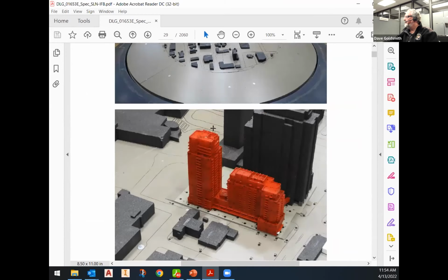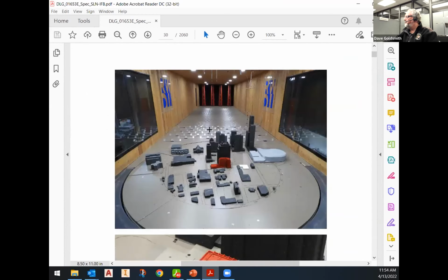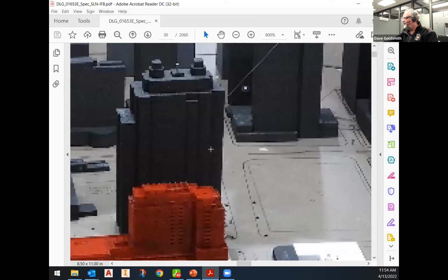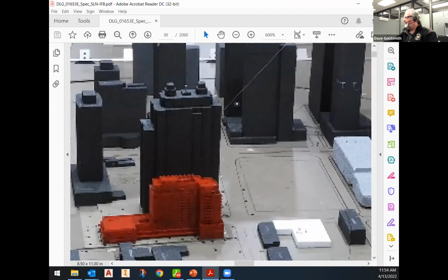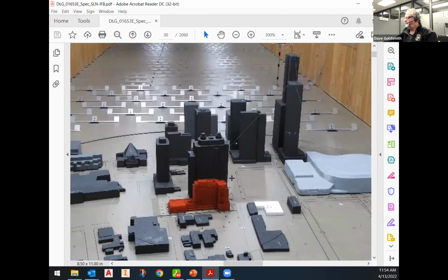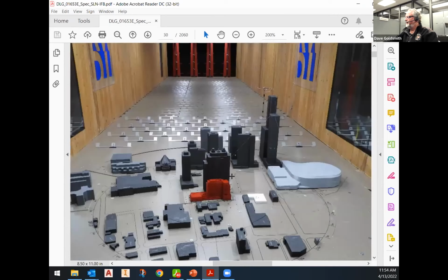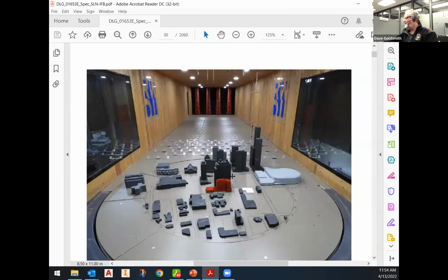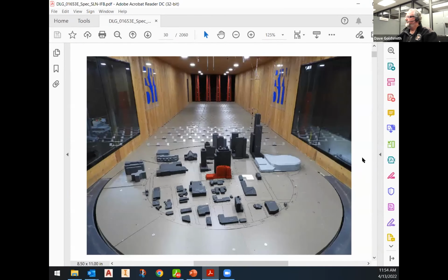So they want to be conservative in all of this because you are in a critical situation downtown, and in particular, you've got a huge building right beside you that might be creating a Venturi effect between the two buildings that can result in really extreme wind speed ups. But that's the science of it. If it's an important enough, critical enough building, that's what you really need to do.